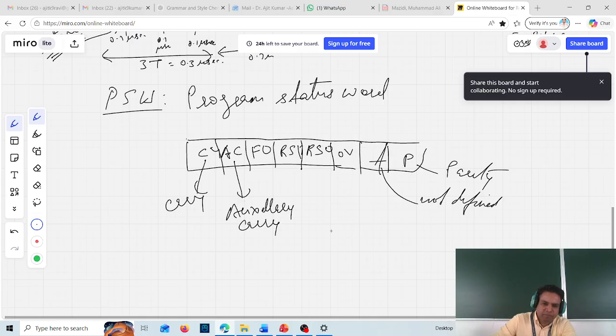So what is happening? Suppose you are adding two numbers or subtracting two numbers. Let's say you are subtracting 4 minus 4 using those programs. Your answer is 0. Now how will the microcontroller know that the answer is 0? Or let's say we are adding 8 plus 8. Then 0, 0, 0, and then 1 plus 1 is 0, and then 1. This extra bit is called carry.